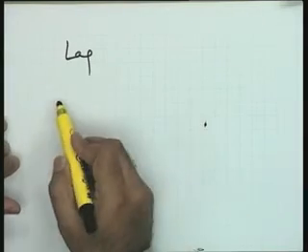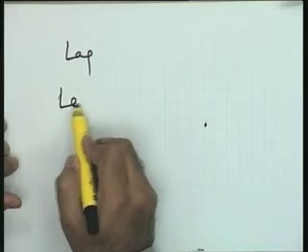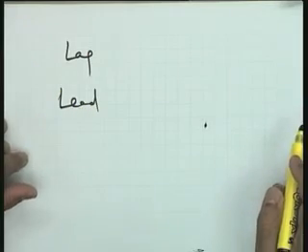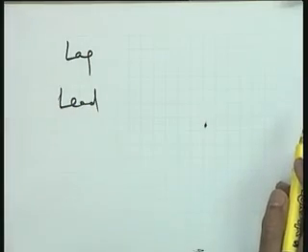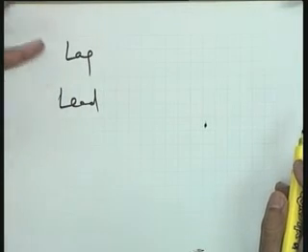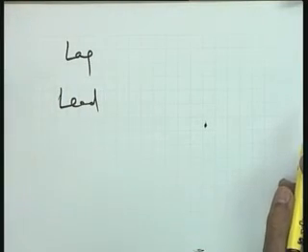If the transient performance is not satisfactory, you go for a lead compensator. That is, you push it so that your transient performance is satisfied and then check whether your steady state requirement is satisfied or not. If not, you cannot say anything. The lead compensator can give you only that much.